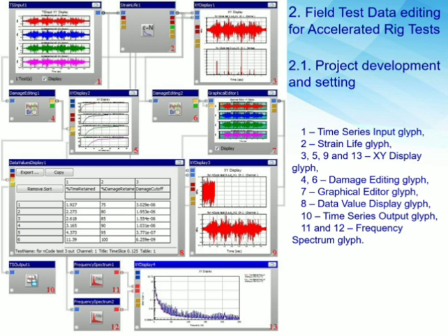The field test data were derived from 4 channels of a universal measuring system. Each of these represents an axial strain gauge placed in some potentially critical locations of the sprayer booms. The task is to edit down these channels to retain all the damage but shorten the length of the files as much as possible. This enables significant benefits in accelerating rig tests.